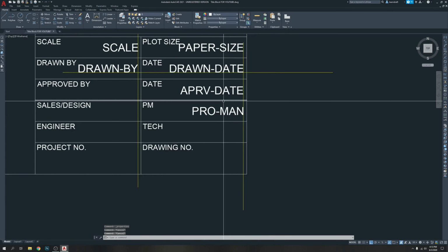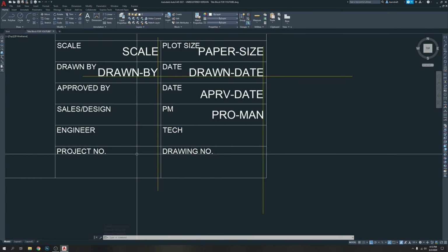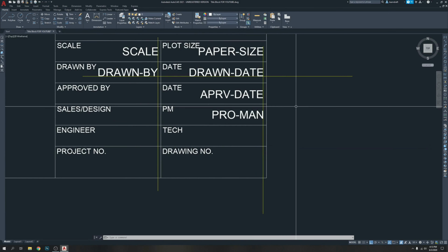now this one looks almost in the middle, but when we draw there, we're gonna align them. Now we need a tag. So which technician is working on it, after you approve the drawing you need to place it. So now ATT, enter, TECH dash name, click right and click OK and bring it here. So it's running because the F3 is on.